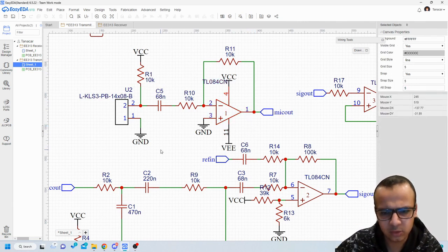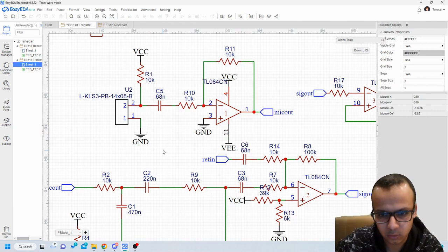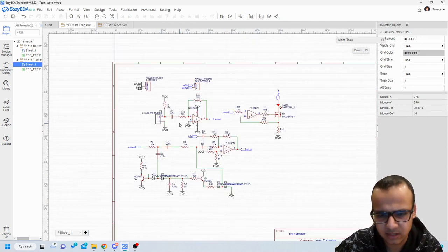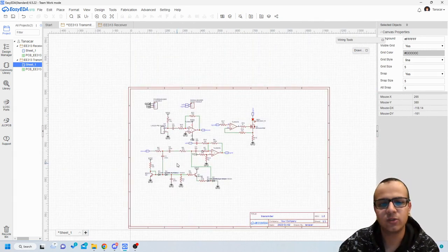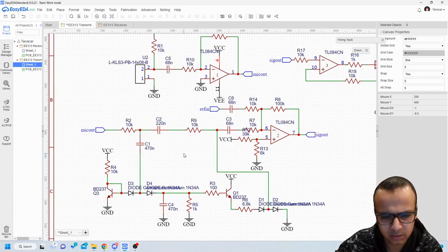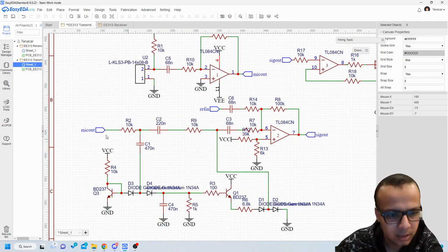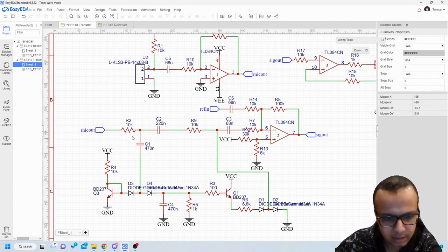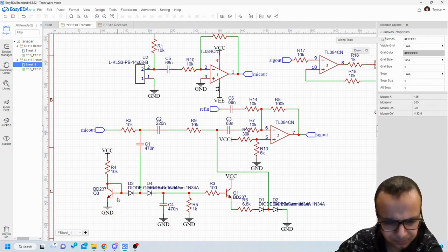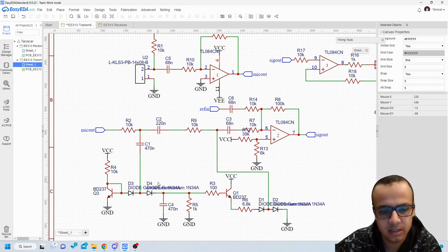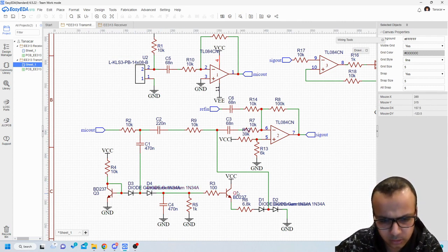After that, we need to control the audio which we are inputting to the system. So we have an automatic gain control here in the second circuit in this unit, which works as follows. It takes the input from the microphone driver, and it detects the peak using this circuit here, using these two diodes and the BJT. After that, this peak is forwarded to the second BJT, and according to the peak, it will determine the current flowing across this BJT.